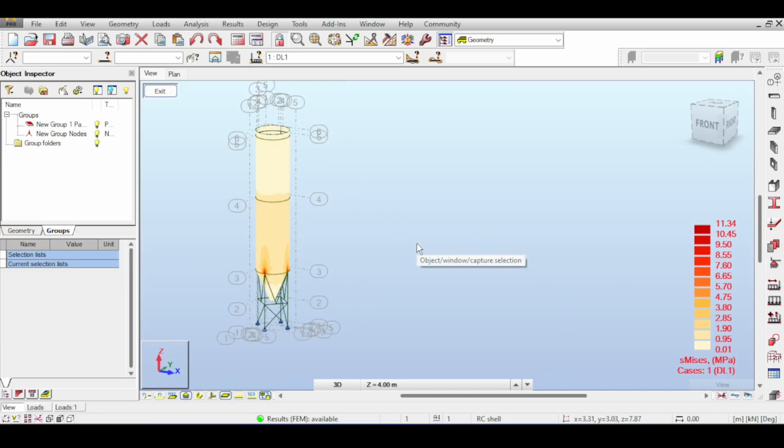You see, what engineers seem to forget sometimes is that they just focus on the operational status of a structure, which is in 90% of your time true. The operational status of the structure is what would determine and control the design for normal buildings. However, for silos, it's a bit different because silos are being transported into place before they are erected. So there are transportation and handling loads that need to be taken into account.